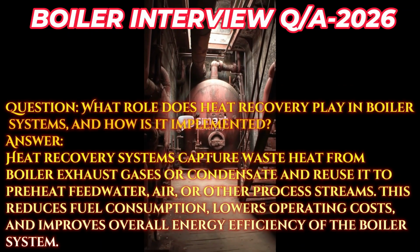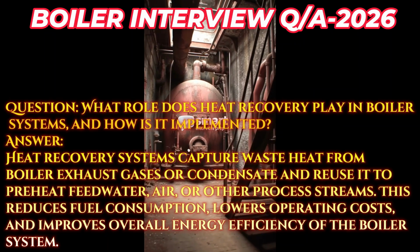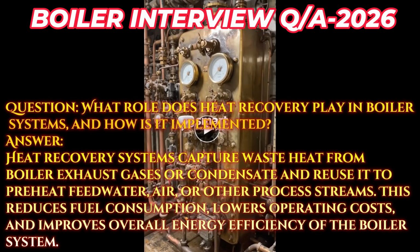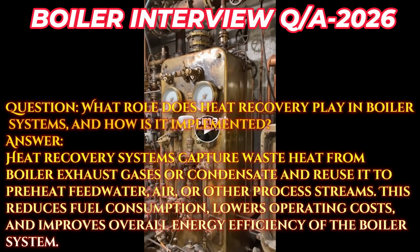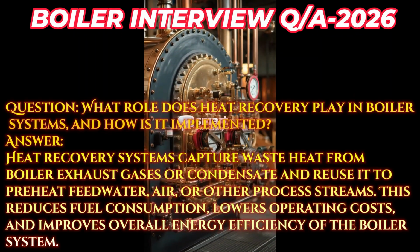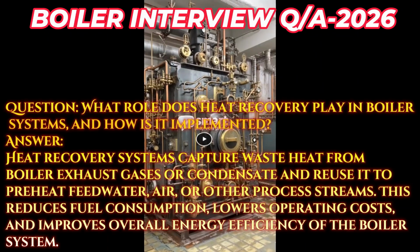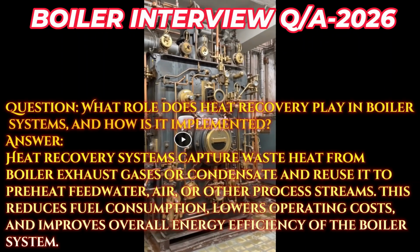Question: what role does heat recovery play in boiler systems, and how is it implemented? Answer: heat recovery systems capture waste heat from boiler exhaust gases or condensate and reuse it to preheat feedwater, air, or other process streams. This reduces fuel consumption, lowers operating costs, and improves overall energy efficiency of the boiler system.